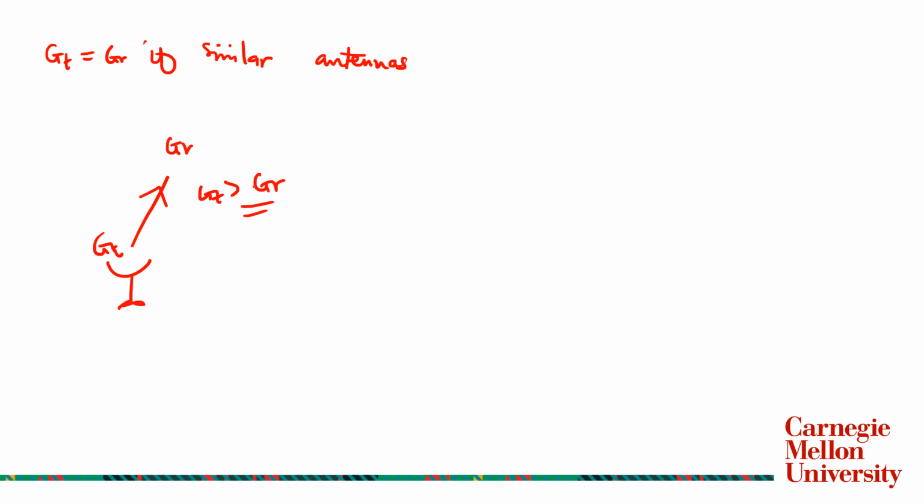The other thing I should tell you is that I'll be teaching a course on antennas briefly, but antennas have a property that we call reciprocity. It basically comes from that English word. The reciprocity property means that an antenna is not designed to work at the transmitter or the receiver. An antenna can work at any side. If you are creating a link and I bring you a bunch of antennas, you don't need to carefully pick which one goes where. Any can go anywhere, unless it's a design decision. So an antenna that can transmit can also receive a signal.